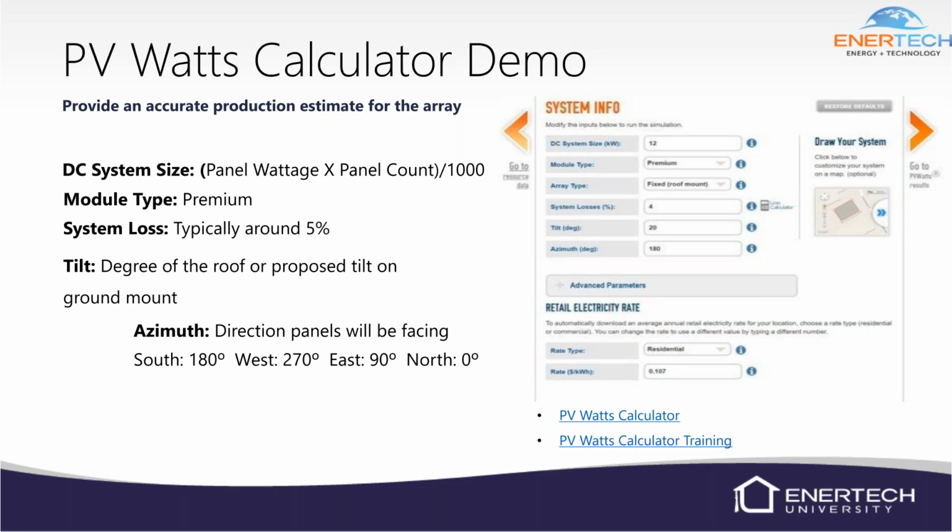We're going to aim for the shoulder seasons and get the best average position out of the entire year. And if it's ground mount and you need more summer direct production, you might go for the 20 degree tilt. So it all just depends on the system design, on when somebody needs power.